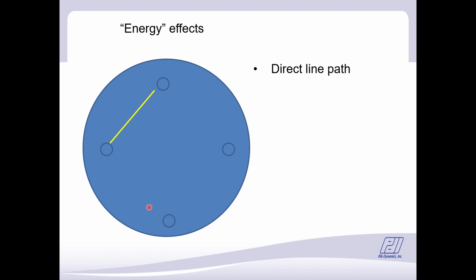The signal goes generally fastest on a direct line between the two tubes. So that's the fastest arrival that it could possibly be. Due to the presence of aggregate and so forth in the shaft, the signal also can follow curved paths from one tube to another due to reflection and refraction in the concrete itself.